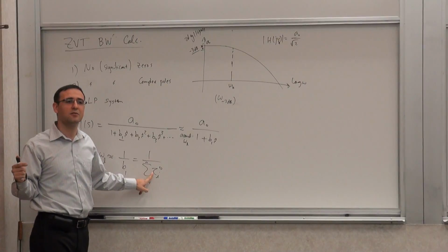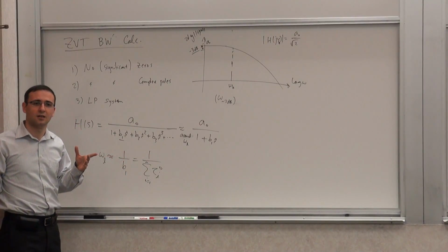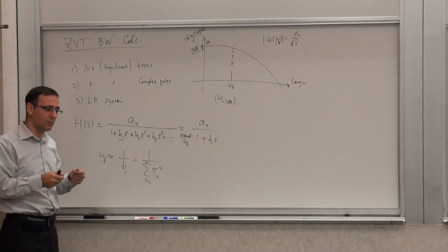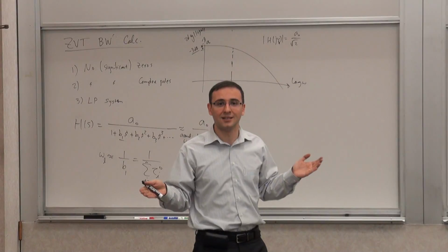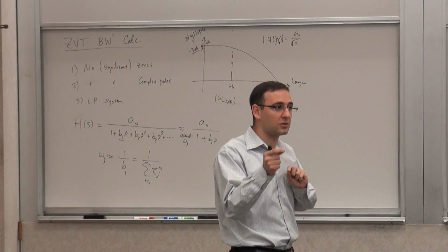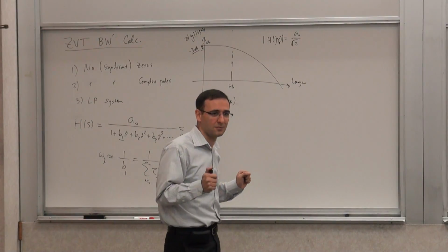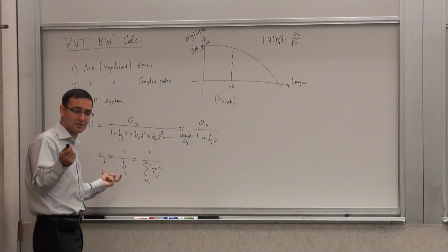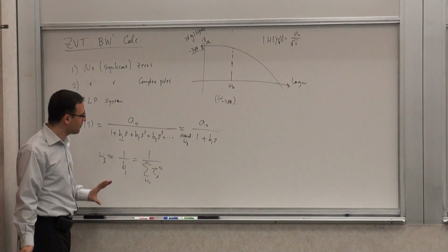It tells you where your major problem is, and that's why it's important from a design perspective. You design a circuit, you look at it, and say, okay, I'm trying to get this much bandwidth, I'm getting 1/100th of that. What is limiting me? And then you go and look at the time constants and see which is the big time constant, or where your limitations are coming from. That's the usefulness, and I will show you real numerical examples of this in a second. But that's how it's used.